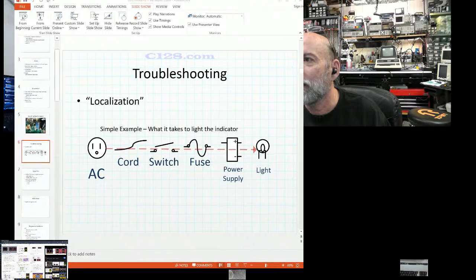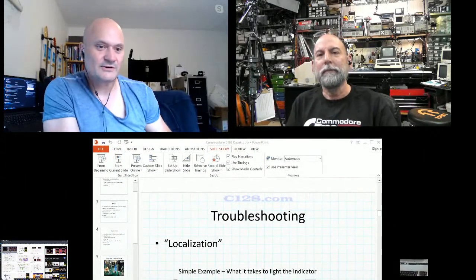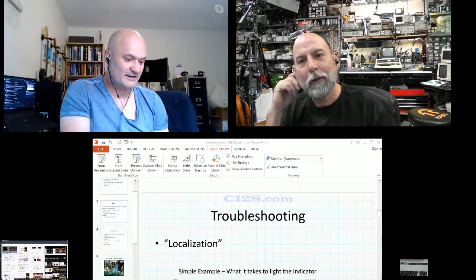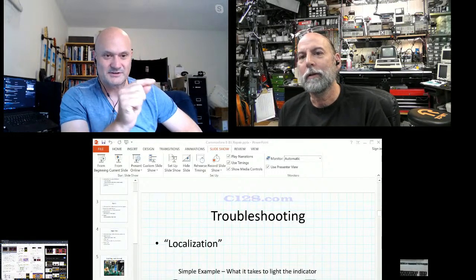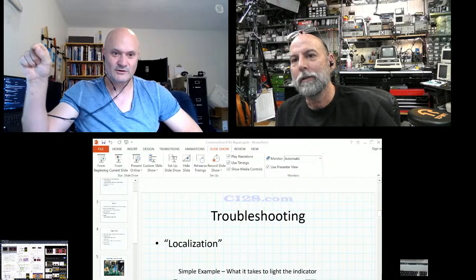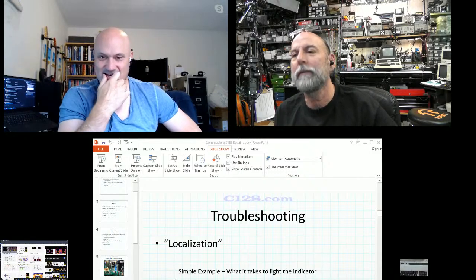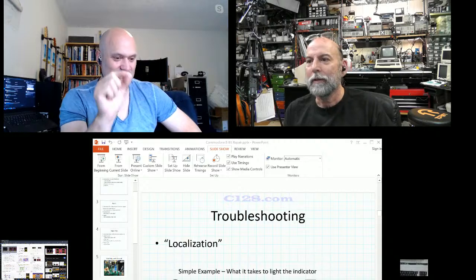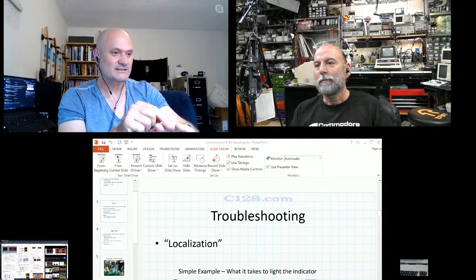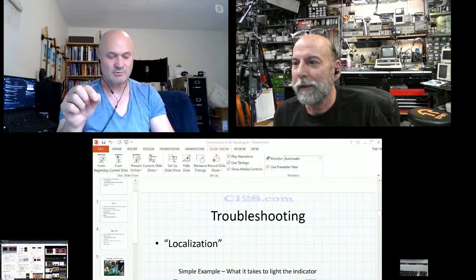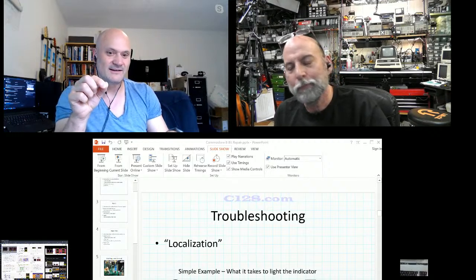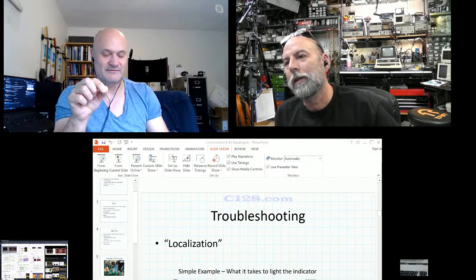You get a signal generator, and you do it in RF. You get a signal generator, and you get a good oscilloscope, and you start at the source, and you trace all the way through the circuit. Right. You go, okay, at this first point, that's my signal. I got my sine wave. At this next point, it should look more like a bit of a distorted sine wave.